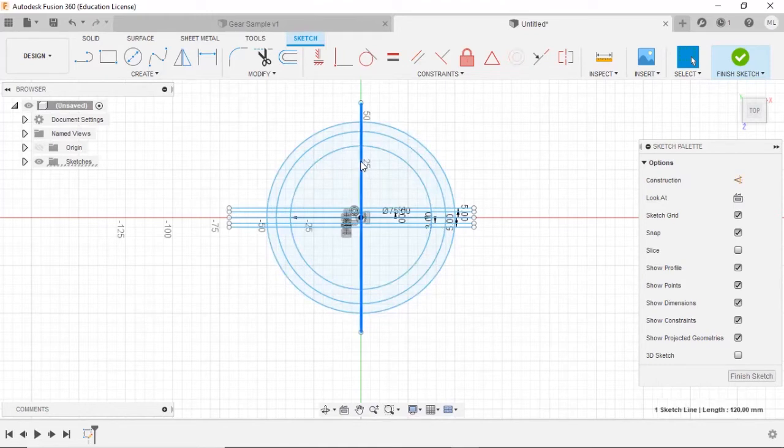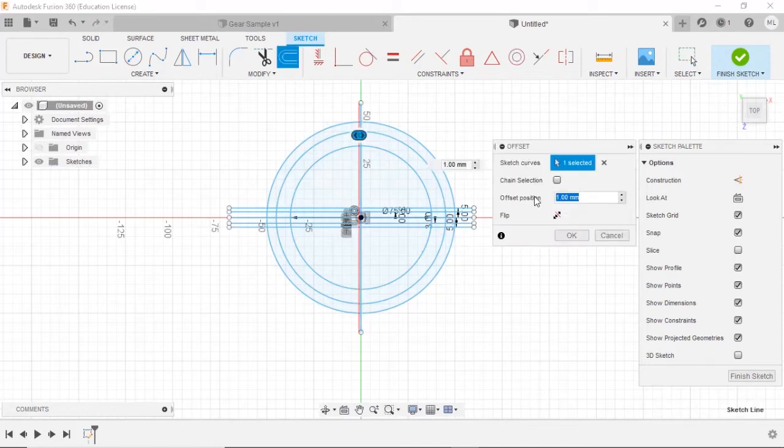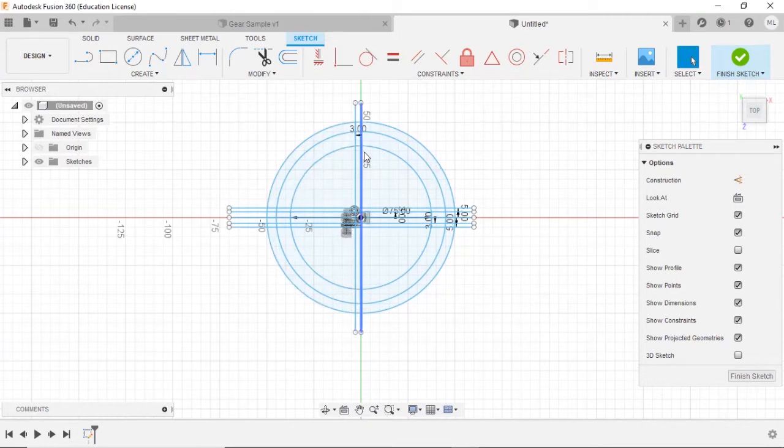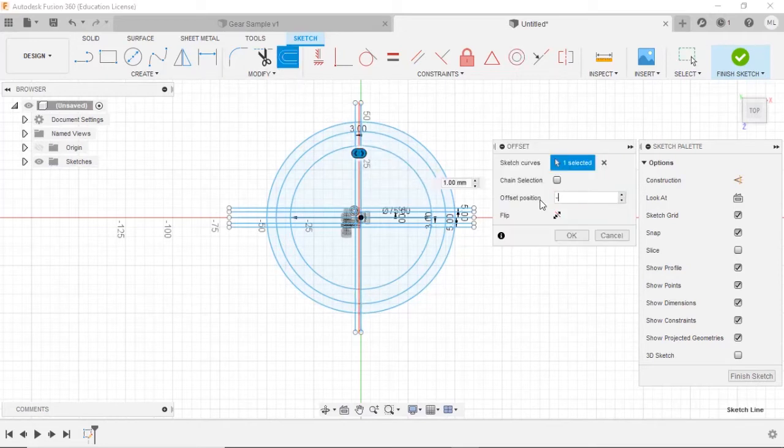Then after that, let's do now another offset into your Y-axis. Since we use here 3, we'll be using here 3. So same lines. So offset, and then create now 3. The other one is -3. So if you are into the positive side, it would be placed onto the left side. If you are into the negative side, you place into the right side. -3.